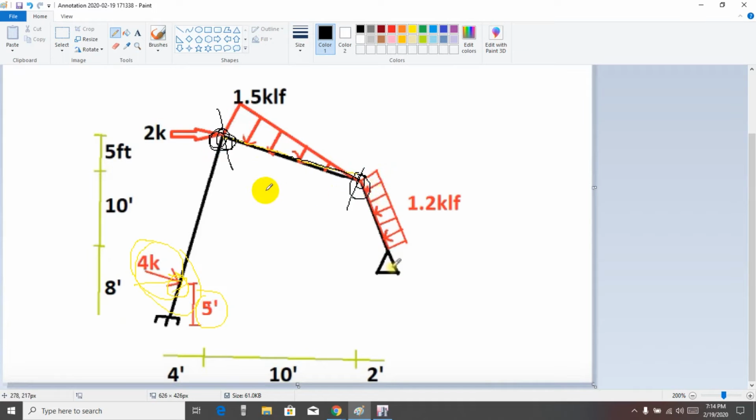And in my previous video I told you that ETABS always considers the lower portion as the first portion. So this is the lower portion, it will be absolute distance 0, relative distance 0, and this will be relative distance 1. How we calculated that, you can see my previous video.